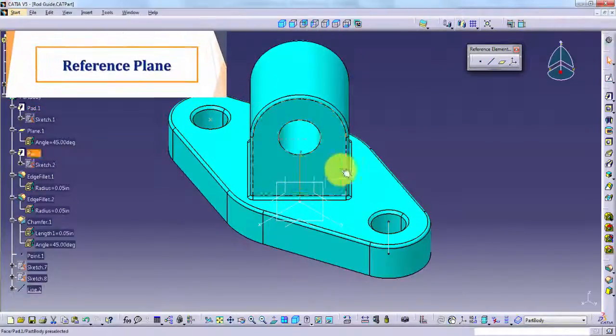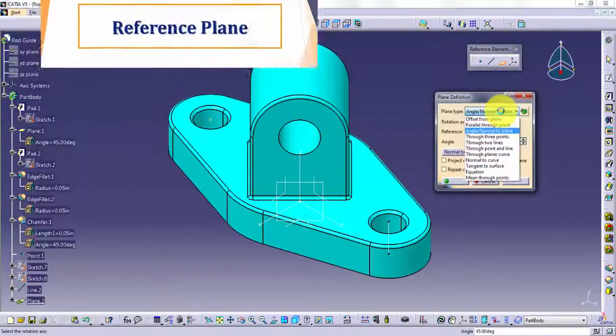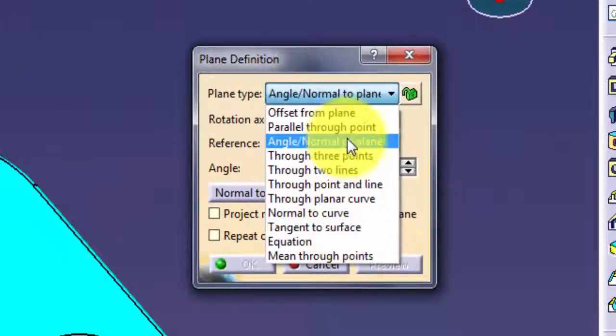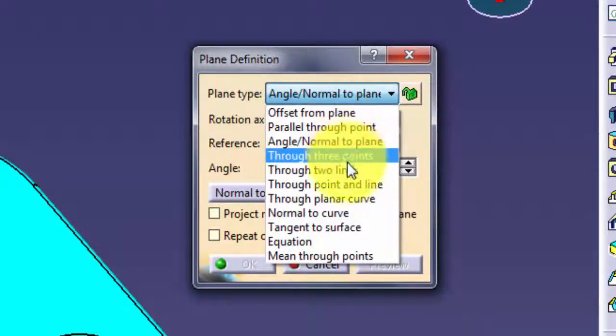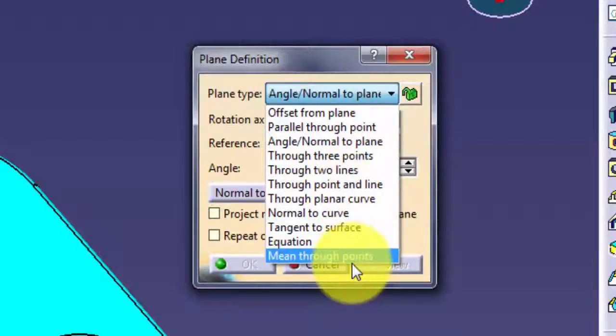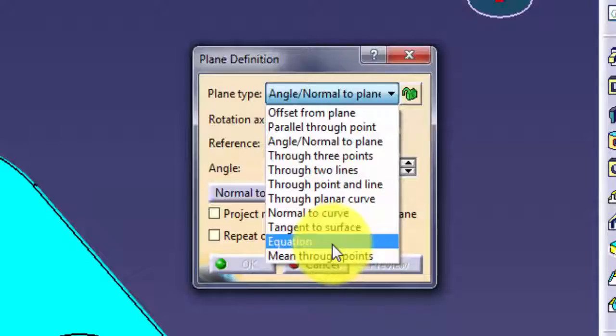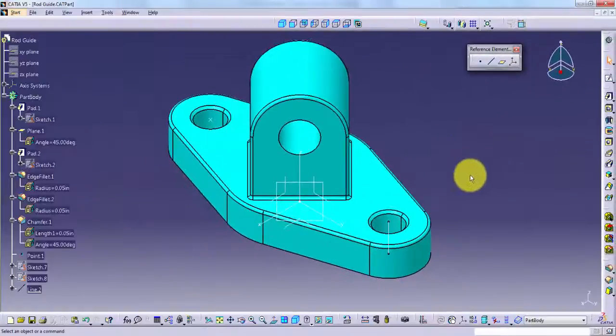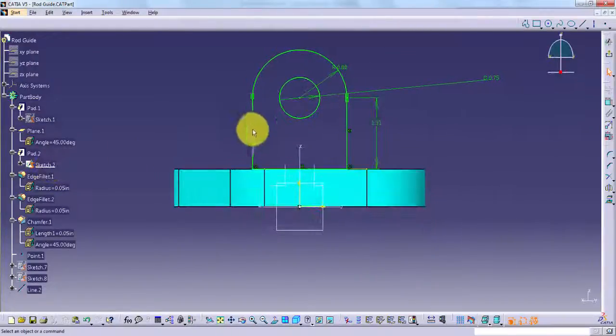A reference plane is a feature and object that represents an infinite plane in space. You can define a reference plane using 3 points, 2 lines or edges, a face, by defining its normal vector, or by defining the plane equation. You commonly use reference planes as a placement face for features or sketches. They are also useful for positioning features, constraining sketches, or splitting solid bodies.